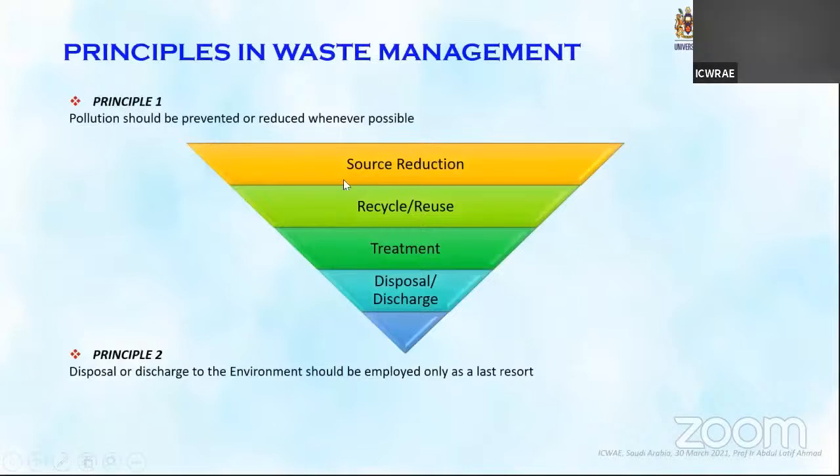I think the principle of wastewater treatment is, whether we can reduce the source, which is impossible. We cannot reduce the source because every single ton of crude palm oil will produce 3 tons of wastewater, which is the effluent. We cannot reduce the source unless we reduce the processing amount; we can recycle or we can treat. So the choice is with us. For us, we recycle, we reuse, we reclaim, and at the same time, we treat, so that the load to the environment is very, very little.